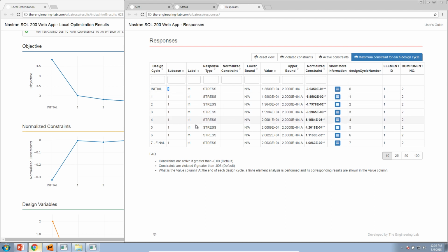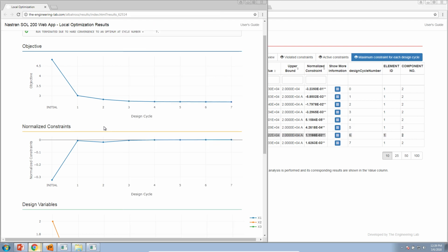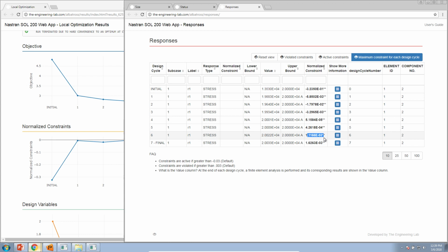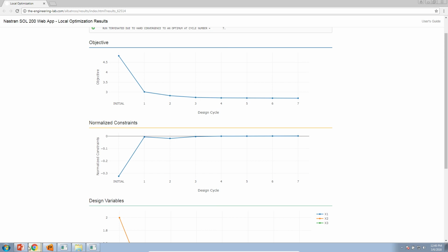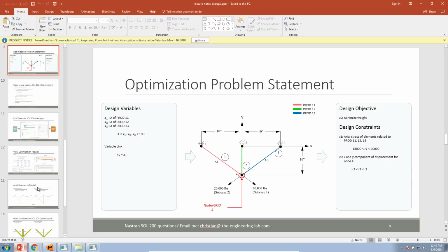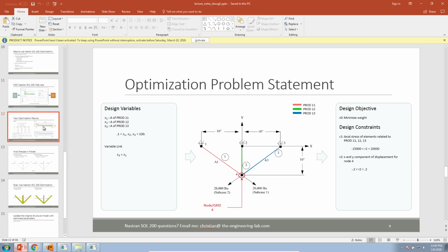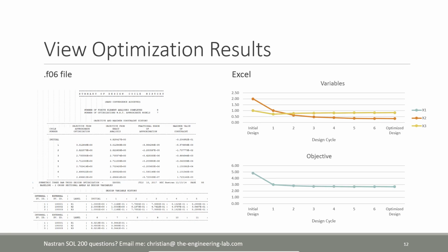And here you can see that essentially element 1 of load case 1 is dominating each design cycle. For the sixth one, it's still element 1 axial stress that's dominating the optimization. So negative 0.001 is the value that's reported here in bold. The reason I wanted to point that out is that sometimes you might have to dig into the actual data and look at specifically what's being done by the optimizer, what quantities are being singled out by the optimizer.